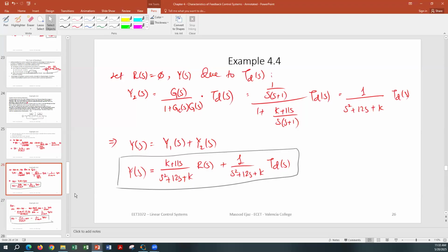We're going to take different K values and plot the error and the output to see what value of K works well for the system. But when you look at the expression, that's what you see. Since K is in the denominator of T_D(s), we need a large value of the amplifier gain, the process gain, in order to reduce the effect of the load on the boring machine.